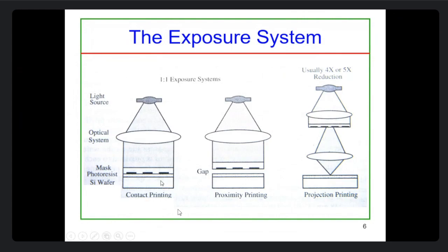whole wafer at a time, almost. Here also the same thing, but here that means the dimension of the lines, or the pattern that you have drawn on the mask, and the dimension of the components that you are printing on the wafer are the same. That is why it is called 1:1 exposure. But here there is a very important point that I missed, so sorry.